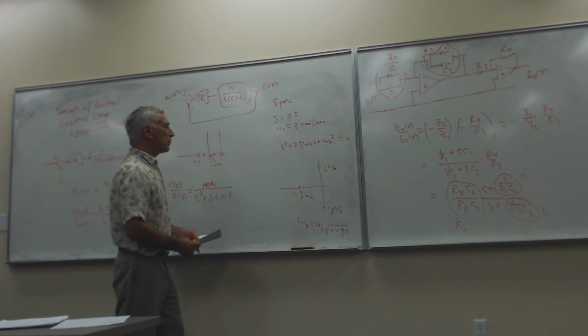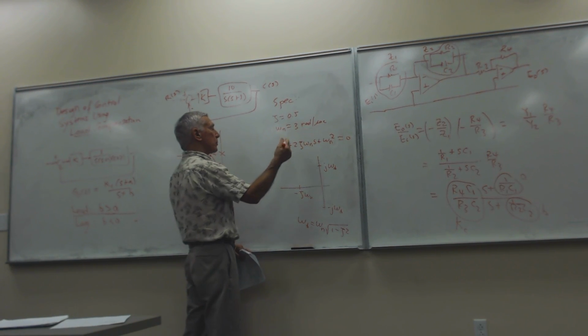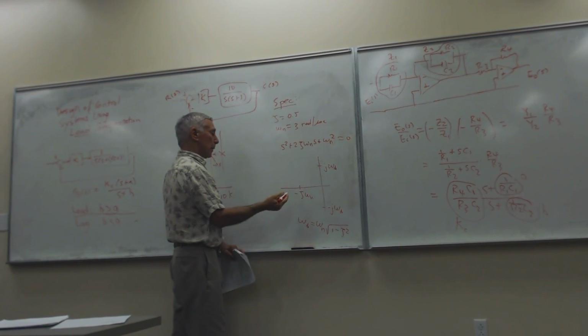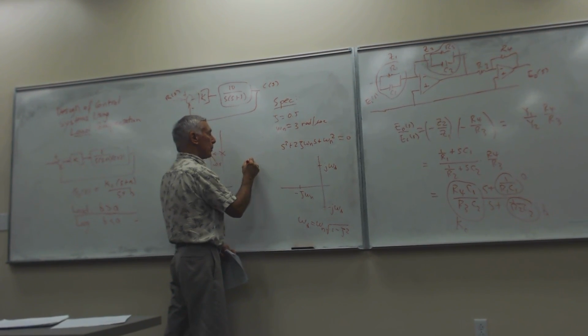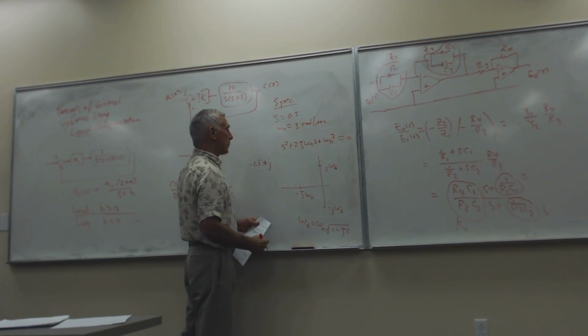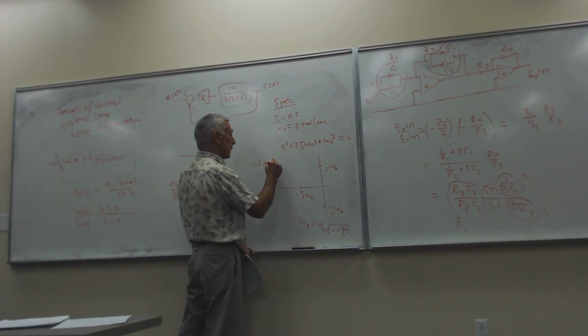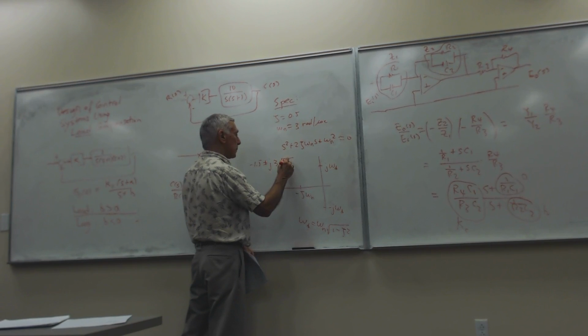And so you see we can determine where our desired closed loop transfer function poles are just using this zeta and omega n, right? They will be at minus zeta omega n, which is minus 1.5, plus and minus j omega d. Omega d is equal to omega n, which is 3, times the square root of 1 minus zeta squared, where zeta is 1 over 2.